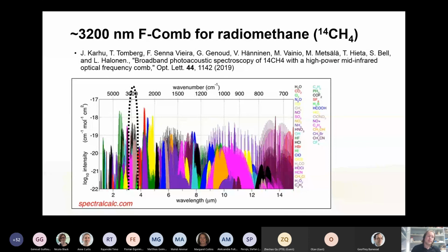If you remember, when I discussed the NDIR example and the difference between NDIR and laser-based systems in my first presentation, I used the broad illumination range to explain why NDIR suffers from interference. But with combs, it is possible to have, in a way, multiple laser sources simultaneously, which can be used to measure a broad range of molecules with good resolution.